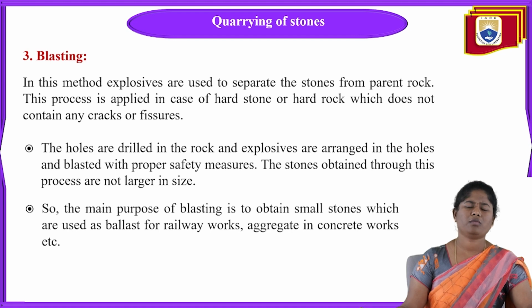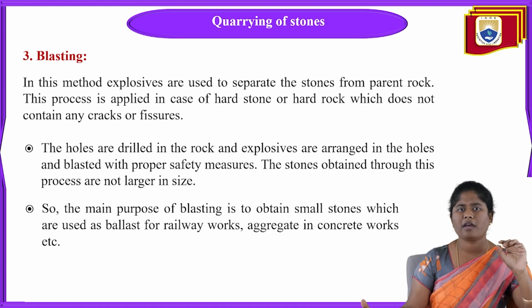Next, after making the holes on the parent rock, they keep the explosives in the drilled holes. When we are keeping the explosives in the holes, we have to take proper safety measures, because the explosives can explode at any time if you do not take safety measures. That's why an experienced candidate should be taken for this blasting process. If the explosive does not explode at a certain time, it can be very harmful to the human beings there. So an experienced candidate is used for this, and the explosives are kept in the holes with proper safety measures.